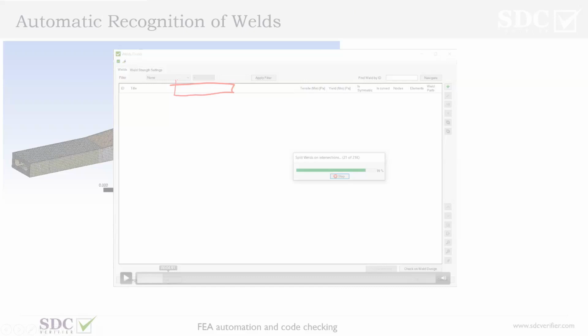But in the end, this spot will pop up, because we still pick up a real stress distribution over the surface. So if there are certain uncertainties, you will still notice a relatively higher stress level at that spot than now. That's already an indication that, okay, better to inspect this spot as well.